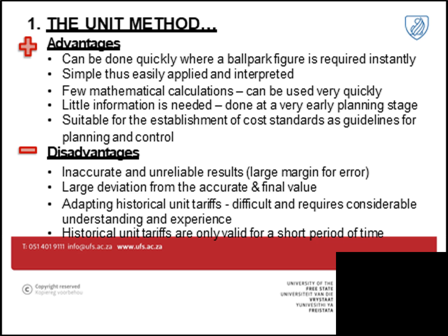So the advantages of it, it's quick, it's simple, and few material calculations are needed. It's suitable for the establishment of a cost standard as a guideline for planning. Obviously, this brings about that it's not that accurate, with large deviations from accurate and final values. The adaptation of historical unit tariffs is difficult and requires considerable understanding and experience. So experience is extremely important when using this method. And the historical unit tariffs are only valid for a short time.